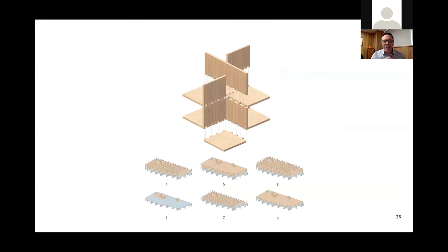And if you're looking at just using the CLT and walls and floors in what we call a waffle system, a honeycomb system, you'll see that they're quite small compartments and little models at the bottom, which is the 1, 2, 3, 4, 5, and 6. I would advise thinking very, very carefully around how you put those castellated joints on the bottom of the wall, because they can take an inordinate amount of time on the CNC.